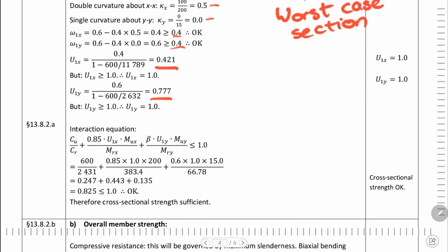And yes, as we suspected, the maximum moments at the end, where the maximum deflection is not at the same place as the moment, so its influence is not as bad. Where the buckling and the P delta effect occurs is not at the same place as the maximum moment, so it's not as big a deal.